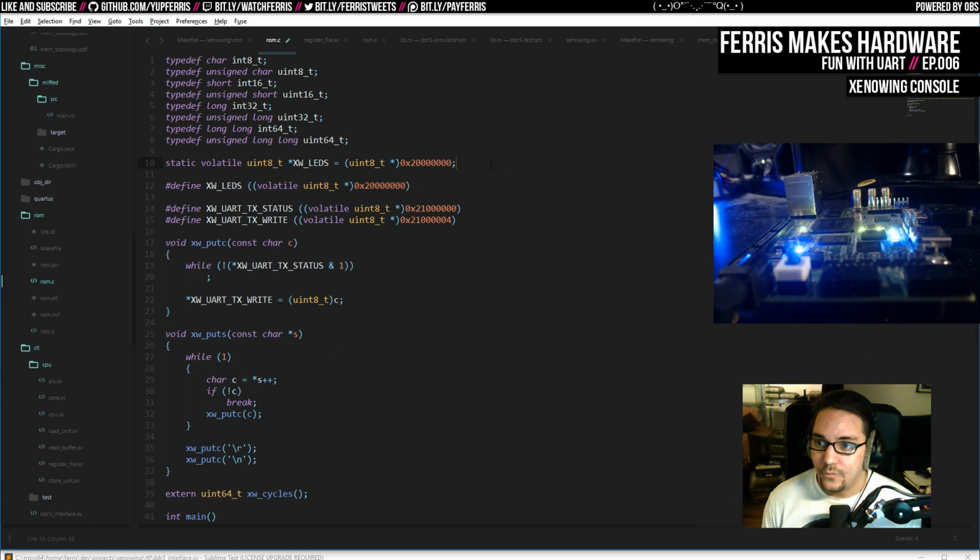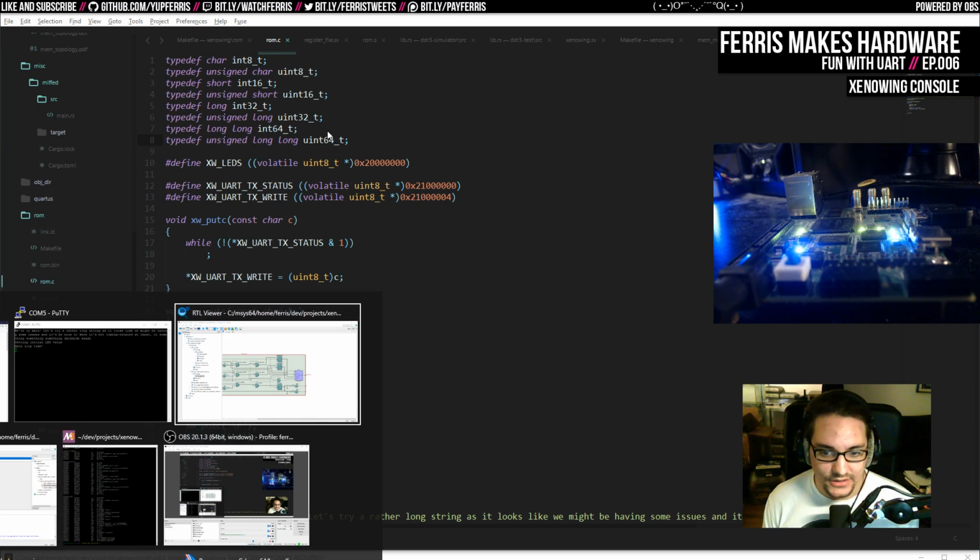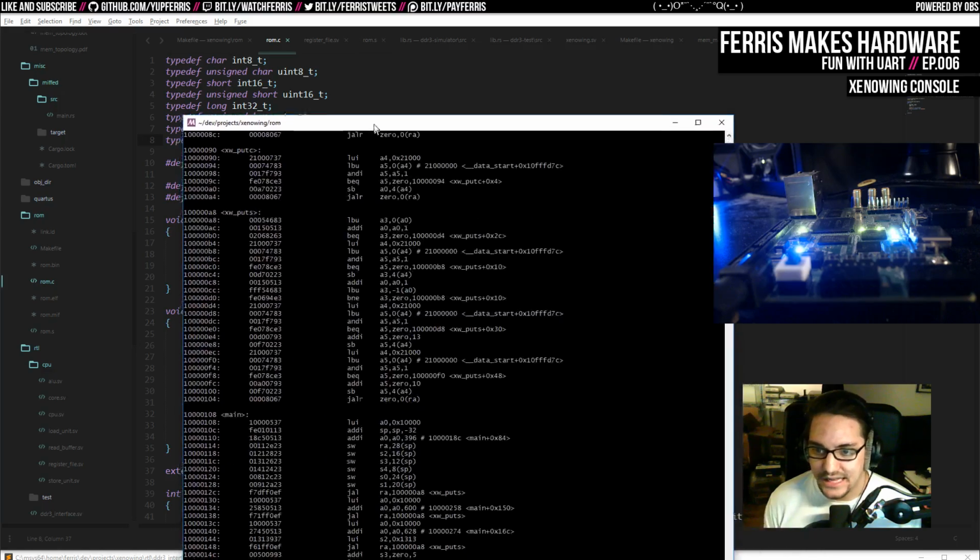What happened though, and this was really weird, I don't know if this is a bug or just not the way you're supposed to do this, is that with optimizations turned on, it decided that these registers belonged in the small data section, which is ridiculous because I gave them a specific address. Somehow it generated code where these symbols pointed to stuff in the small data section, which was not good. So I spent a while today trying to debug what I thought were totally my fault in the CPU implementation, only to realize when looking at the disassembly that those symbols had been placed in the wrong place.